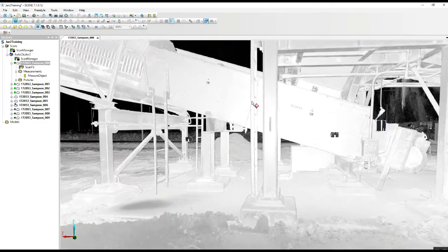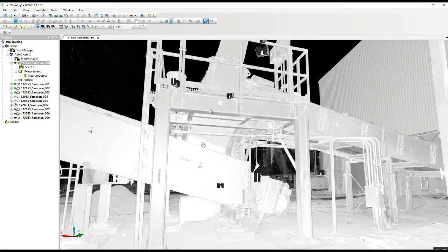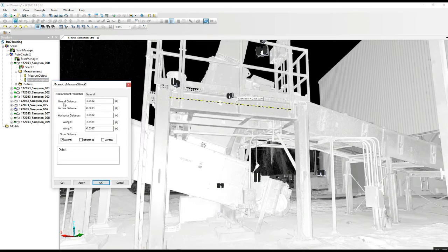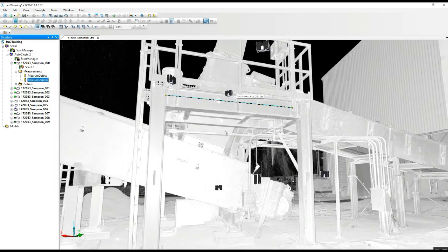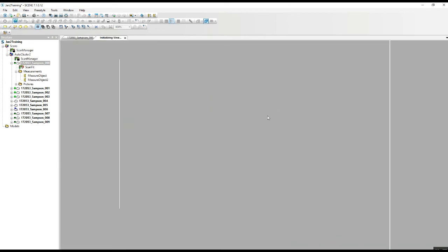And we can go something as simple here as our I-beams. Once again, we can choose a, this time, horizontal measurement. We don't want to get any sort of an angle that'll throw off the actual measurement of the equipment. Again, rectangular selector, right click, 3D view.